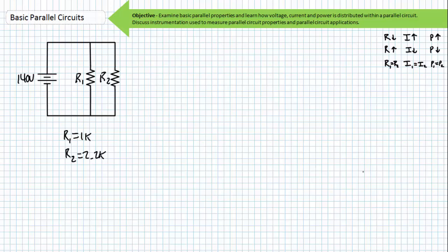If current through a single element ceases, and all elements in the remaining parallel combination continue to draw their rated current, how will an open element affect source current? Obviously, with decreased current draw, the source current should go down because with the removal of a path, the total resistance seen by the source will go up.